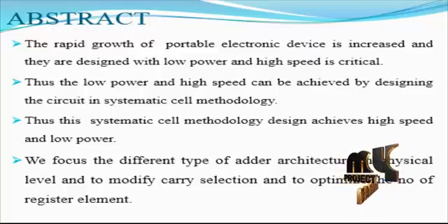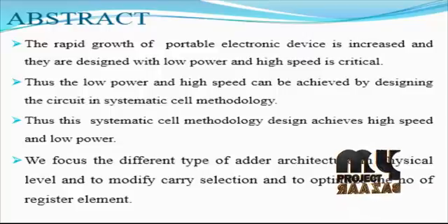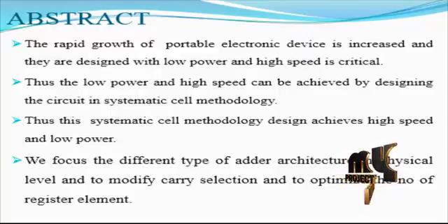The SCDM divides a circuit structure into a main structure and an optimization correction mechanism. The main structure has features including the least number of transistors in a critical path and fairly balanced outputs, being power-ground free and symmetric. The mechanism has the duty of completing the functionality of the circuit, avoiding any degradation of the output voltage, and increasing the driving capability.